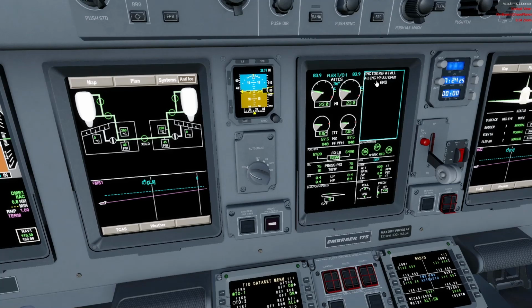The ice detector takes over. If ice is being detected, they would stay on. If not, they would turn off. If they do, remember what we said, if an ice condition exists, we would also see this condition here, and also we would get stall protection ice speed.